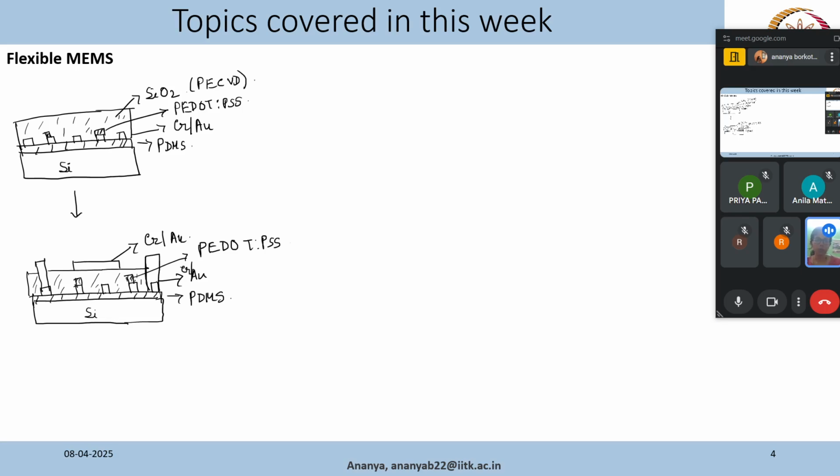We already know that wet etching is very selective, because hydrofluoric acid will etch out SiO2, not some other material, whereas it will not give us very good directionality, so the side walls will not be sharp. Whereas for dry etching we will get very good side walls, but it will not be very selective, it will etch away everything. If the energy of the atoms and ions is sufficient to remove a layer, then it will remove it. So it's not selective.